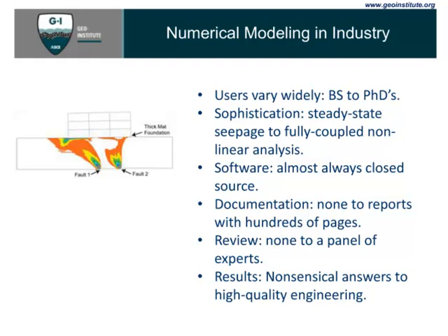The sophistication of the kinds of models that are used in industry varies all over the place, everything from very simple steady-state seepage analyses for flow nets under sheeting to very complicated fully coupled nonlinear analyses for earthquake applications and dams. The software that's typically used in industry, in my experience, is almost always closed source. I've never seen open source used, even though it would be a great idea, I think. Most of the software is Itasca's FLAC and Plaxis and similar codes.